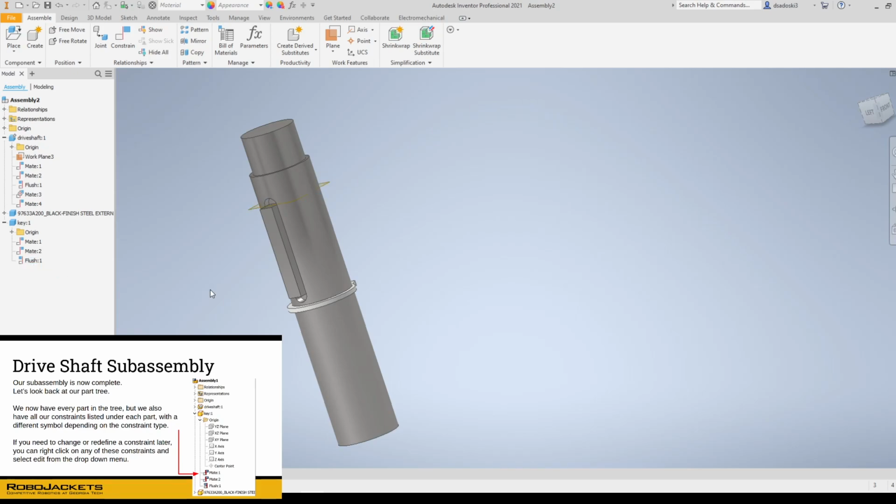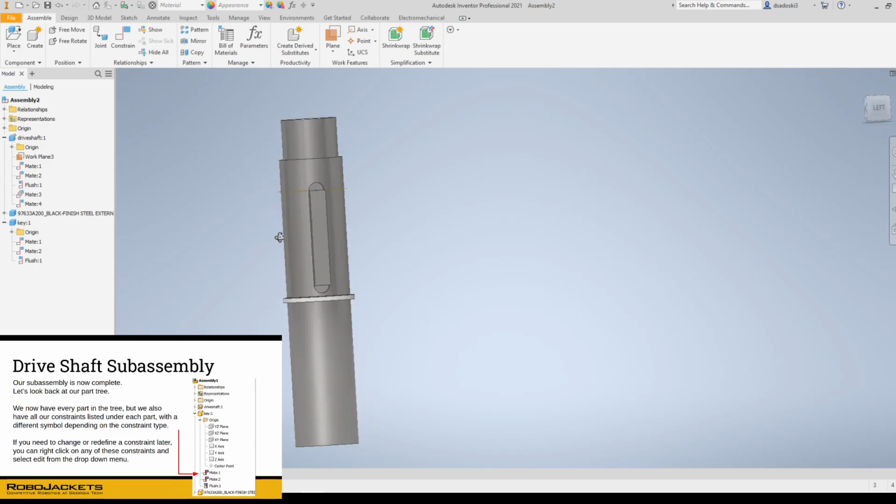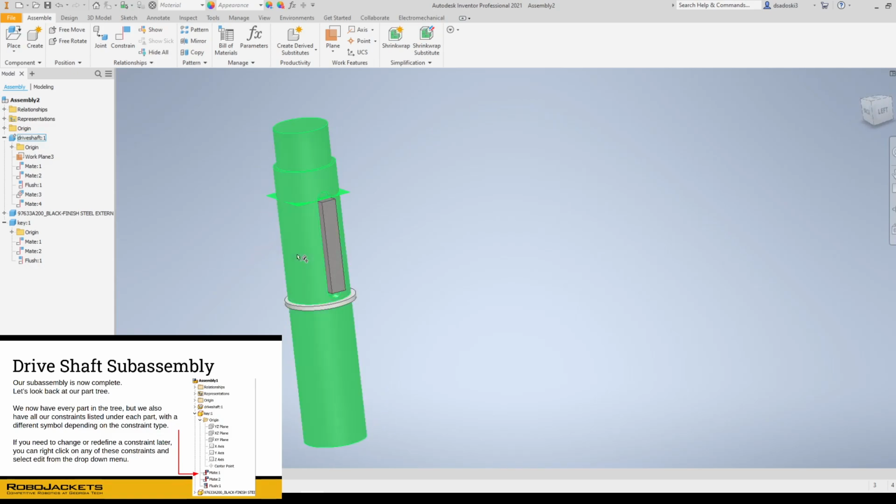A really cool thing you can do, and I really suggest it for whatever parts you're working on or whatever assemblies, is if you got time, just name some important relationships. Maybe not for the keyway because these are very simple, but maybe for the retaining ring. Just naming some of these relationships will make it easier in the future to identify problem ones or to identify ones you may want to remove without having to mouse over each one and see what each one does.